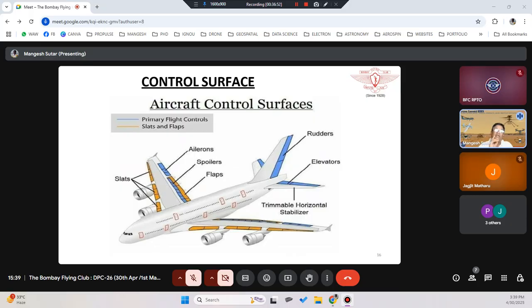Either you create a square, a triangle, a rectangle, or a circle, whatever is instructed to you. And then again with different control surfaces. Like I would tell you, only use pitch and yaw, or only use roll and yaw. So you have to apply controls accordingly on the drone. That is how you will learn how to fly your drone. Clear? Any questions here?